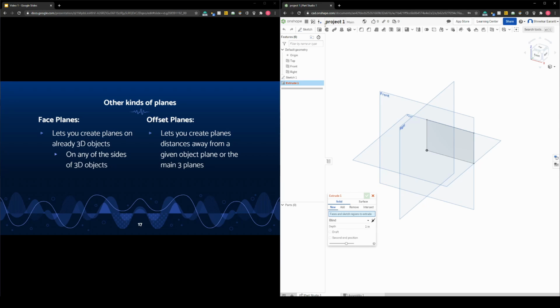But you can just know that you can click on extrude on any object, and then you can say, for example, I want to make it a 3x3x2 square. So I give the depth of the extrusion 3 inches. Now it's 3 inches in this direction. It's 3 inches in this direction, and it's 2 inches in this direction. So I have a 3x3x2 square, right? So now I have an object here. You don't really have to understand how that occurs. Again, I will explain that in the next tutorial.